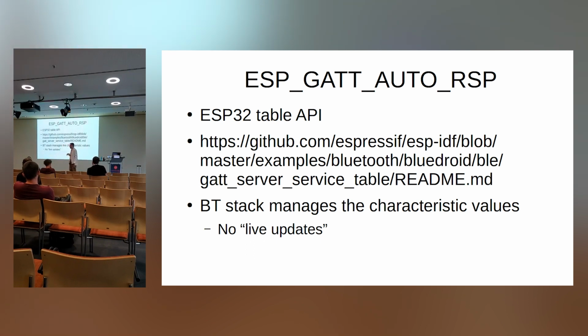Been there, done that. In the declaration, you see the flag auto response. And when this flag is present, the characteristic values are managed by the Bluetooth stack and not by your application. And this means that you still get a read request notification, but the data you give to the operating system gets discarded. Silently, without an error being thrown. This is the one takeaway. Trust me, you spend 20 hours in the lab. I worked 2 days until I found this.